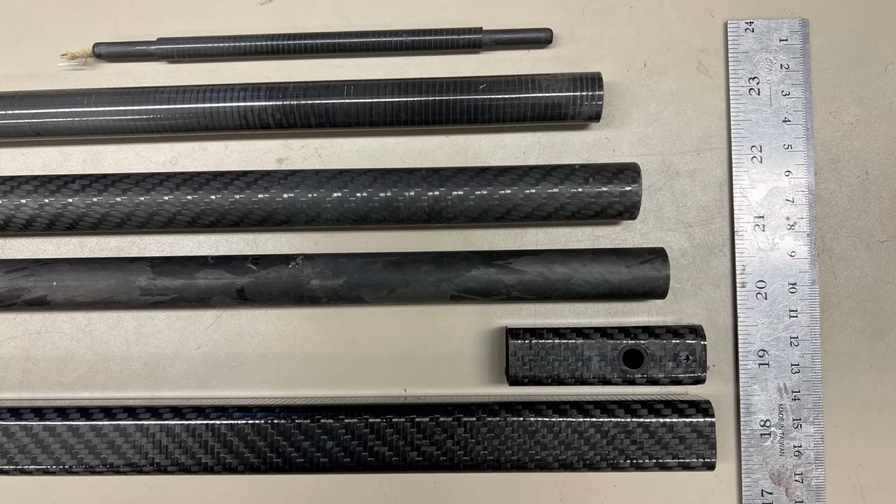Here we have a lineup of all the carbon fiber tubes used over the years. As you can see, there's two distinct types of them. From the top, you can see the first one consists of an inner protruded carbon fiber tube, which is reinforced by a filament winding with a 90-degree grain direction tube on the outside. If I recall correctly, this was used on a locking mechanism for a wing folding mechanism a few years ago.